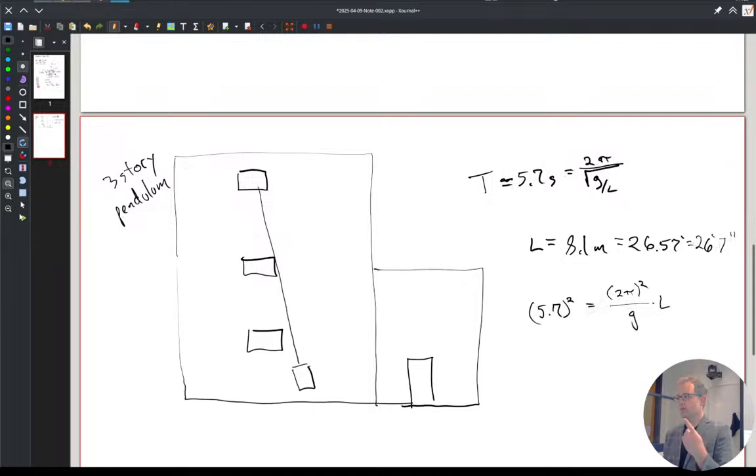So here we were kind of doing the opposite calculation, right? Measure the time period, can we figure out what this structure looks like? And we hit the wall. There was wind, there were a lot of other things happening, but time period, natural frequency, is called natural frequency because it's such a stable value. It's pretty easy to measure most of the time. Sometimes there's other stuff that gets in the way, but we're doing pretty well. Within 1 inch is pretty good for even all those other things happening.